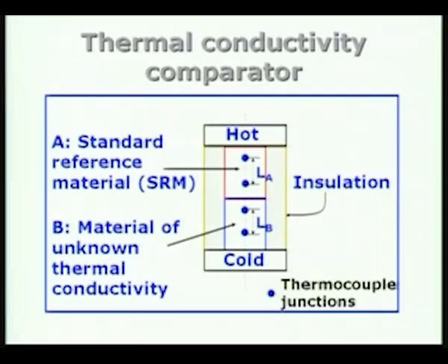thermal conductivity comparator, and it is very useful when you have the sample available in the form of rods, cylindrical specimens, and if you have a standard reference material, SRM, whose thermal conductivity has been documented extensively and is available in the literature, then we can take that standard reference material as one of the materials and prepare, as shown in this particular figure,